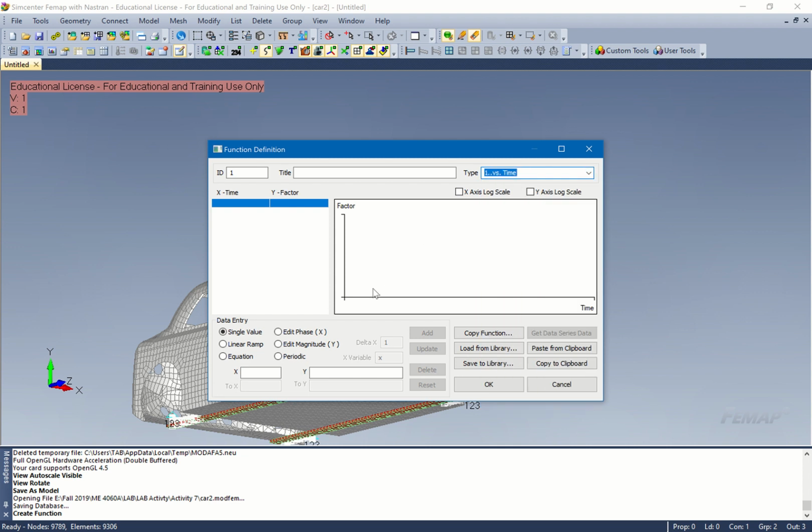Now, we're gonna start at 0 with that sine. So the variable is equation. Variable is x. And we want to have delta t of 1,000th of a second. So that's delta x would be 0.001. That make sense? Cool. And we wanted to have that pulse duration equal between 0 and 0.051 seconds. That's going to be the duration of the pulse of that input. Does that make sense, everybody?